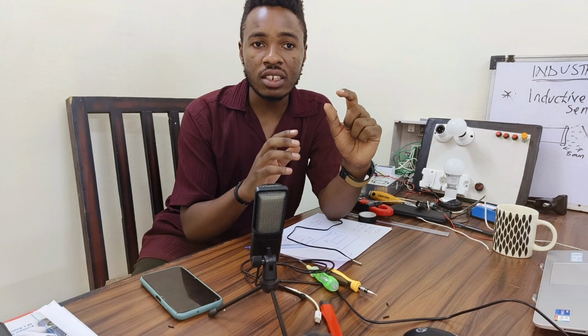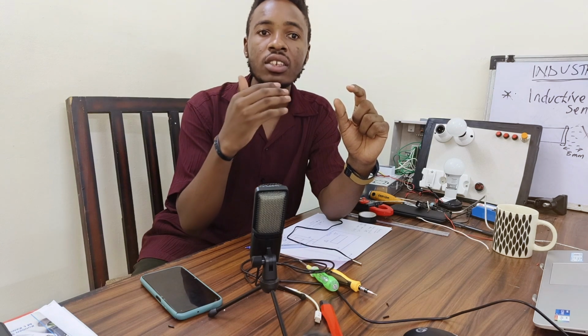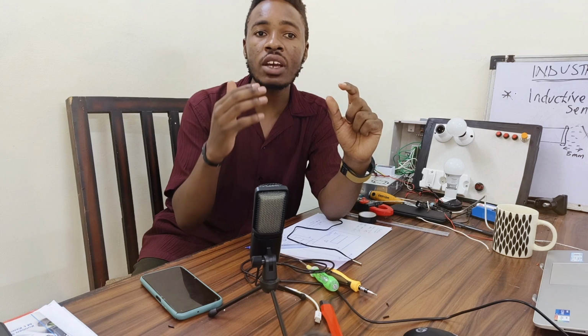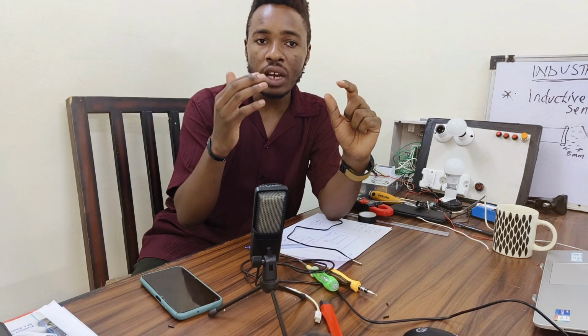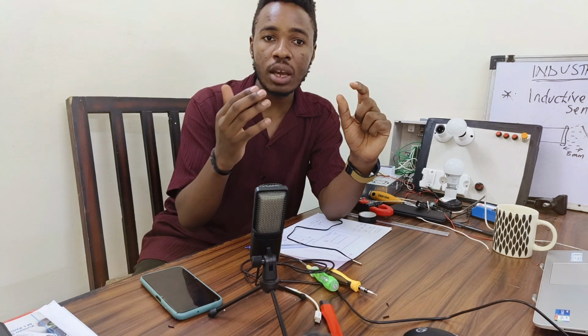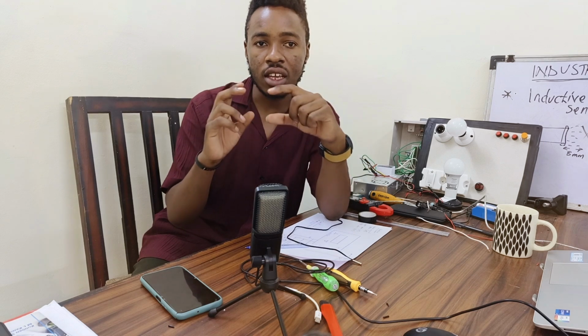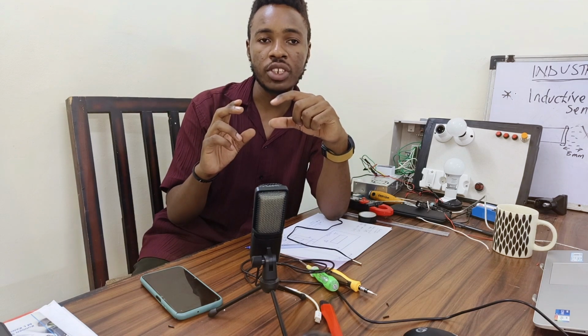If it is at 30, it does not turn off the heating. It will just heat until it is at 31.5, and then it turns off and falls back to the cooling level. Whenever it is at 30, it does not immediately turn on the heater, but rather turns it on at around 29. So that's the logic in control of temperature. Thank you.